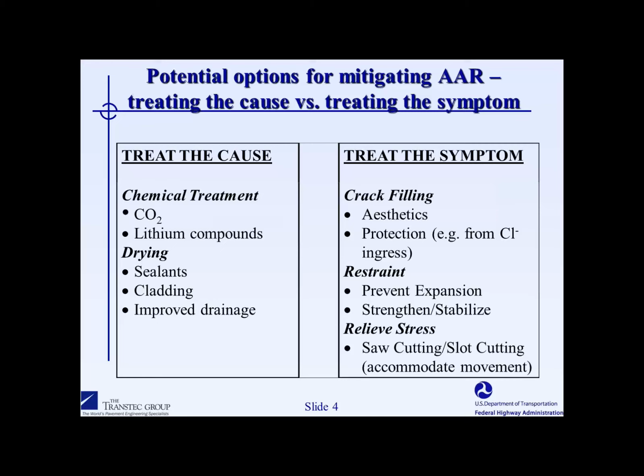theoretically one could treat a concrete structure by injecting CO2 into it, and the purpose of that kind of a treatment would be to reduce the pH of the concrete pore solution and thereby slow down or stop the dissolution of the silica and the expansion and cracking. However, this really isn't very feasible from a practical point of view, and also from a technical point of view.